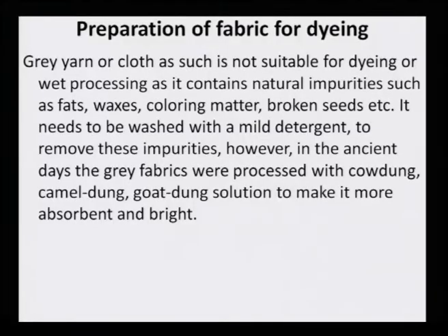Preparation of the fabric for dyeing. Grey yarn or cloth as such is not suitable for dyeing or wet processing, as it contains natural impurities like fats, waxes, coloring matter, broken seeds, etc. It needs to be washed with a mild detergent to remove these impurities.